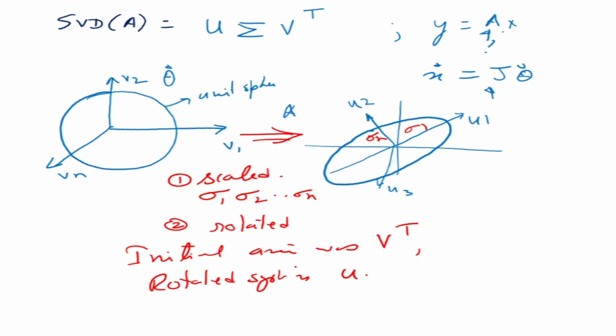So what does this matrix do? The matrix is an implementation of a linear operator. So this J is taking the input of the joint angle velocities, scaling them and rotating the axis, and making that the end effector velocity. That is what it is showing.